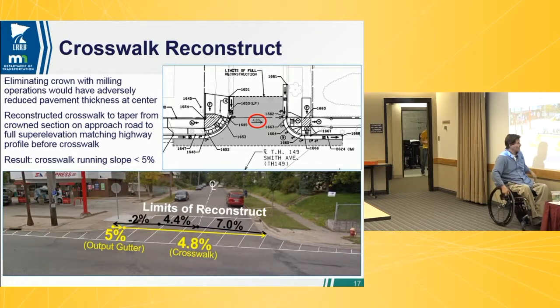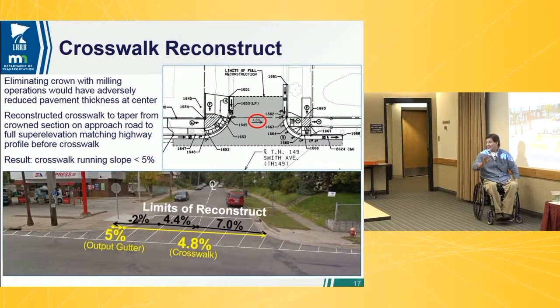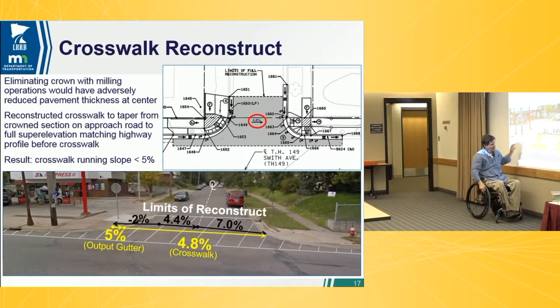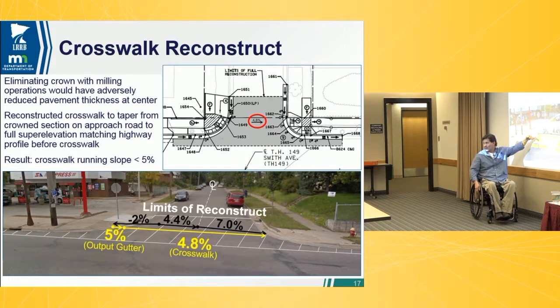And I'm making the peds go down, up, wheeling up this. I get the fact that I'm going up a 5% hill, but that doesn't mean we can go up and down this 5% hill many times. So follow that same grade through here. And actually, we've got an upstream catch basin on this side. So I'm confident even going gutter out here. We've got a lot of our water caught here. We're going to reconstruct this. Gutter out, just let this ramp come down, gutter out, follow it all through.